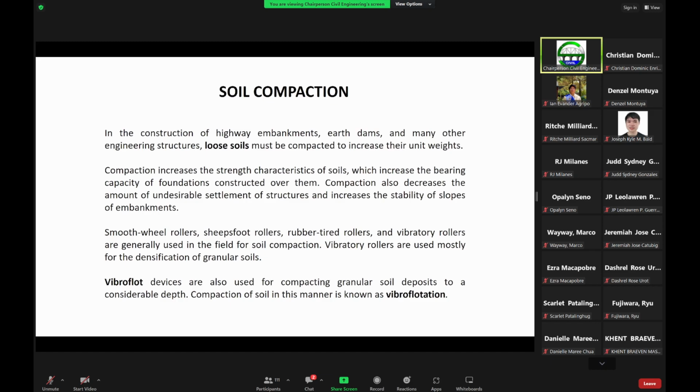Okay, so say below 3 meters, for example, wherein it can no longer be excavated by normal backhoe equipment. Normally for backhoe equipment, we can only excavate around 3 meters, if that's the short arm backhoe equipment. If you have the long arm backhoe equipment, then usually we can still excavate around 5 meters, 6 maximum. But beyond that, you can no longer do excavations.